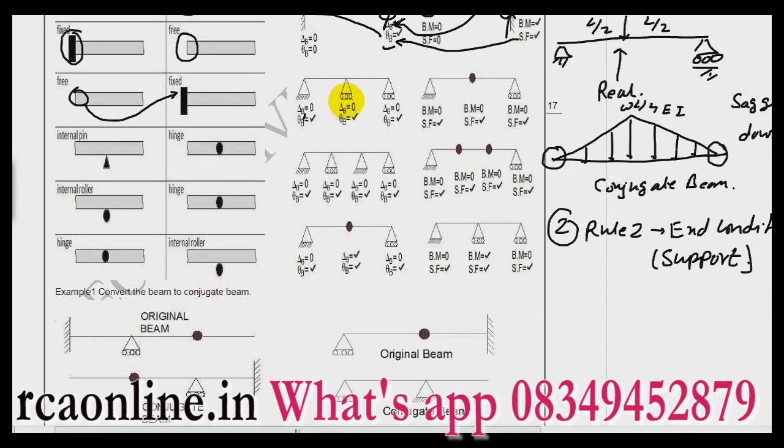Now let us take another condition, which is an intermediate hinge or roller. At an intermediate hinge or roller, I will have delta 0 and theta will be there. So there will be slope because its deflected shape will be something like this. So I will have delta 0 and theta will be there, because the slope is there for the hinge.